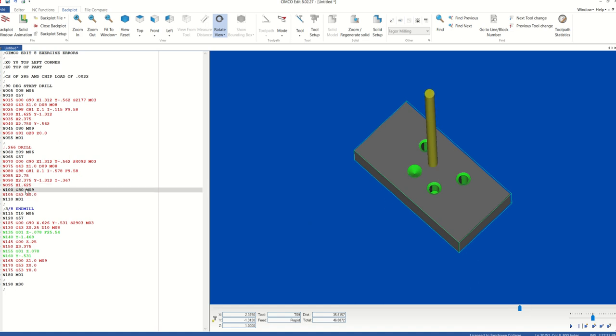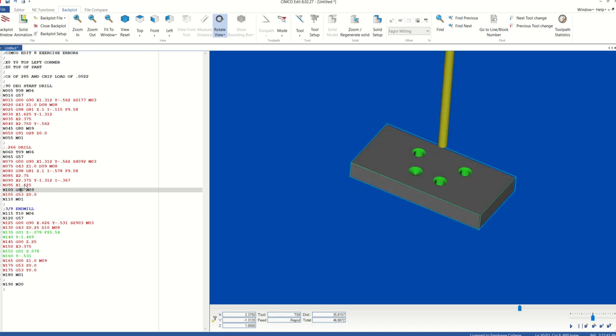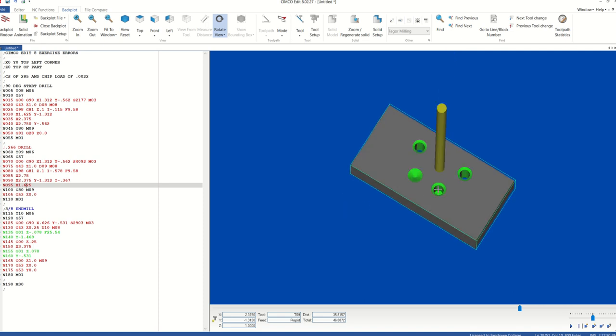You're going to see that I'm at my G80 command. Why did it not read this command line here? So something is wrong with this command line, and this is something that I do not really like on SimCo Edit, is because it'll just kind of, like what you saw in that animation, it will stutter. It won't give you an alarm, which kind of annoys me. I feel there should be a big red bar come across being like, yo, there's something wrong with this command line.